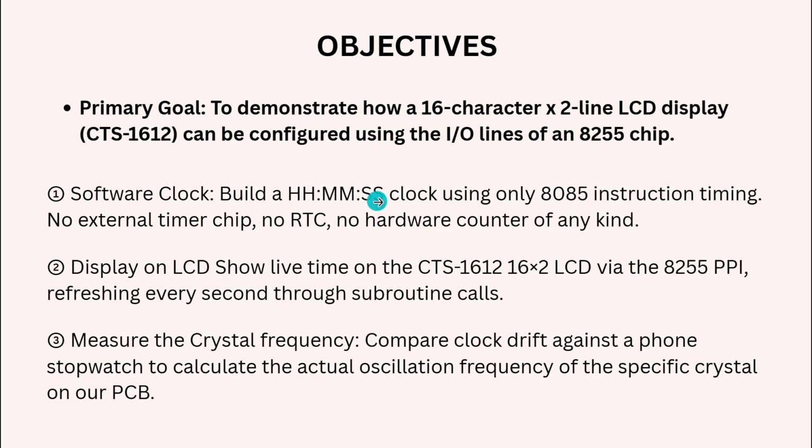The second objective is to display the time on the LCD screen. For this, we just have to connect the display to the 8255 programmable peripheral interface chip, and it must update every single second. The program we wrote achieves this through subroutine calls, and I will also explain what a subroutine means in further slides. The display is refreshed every single second to show the updated time.